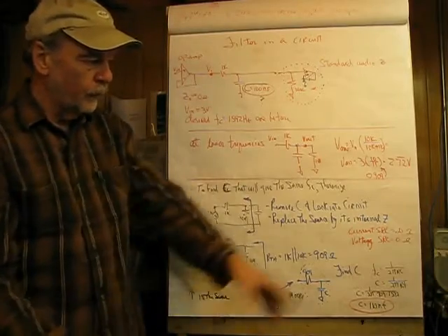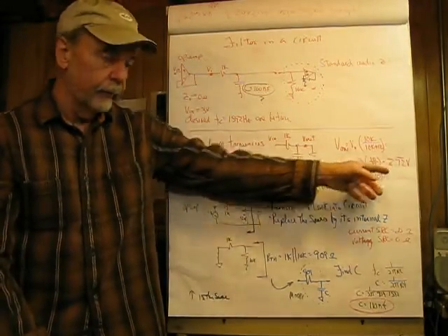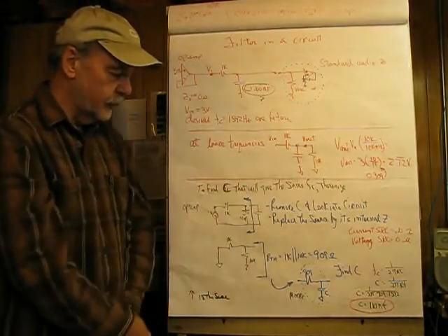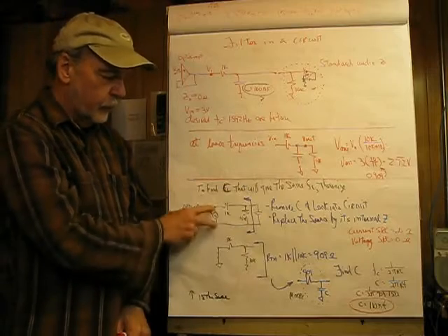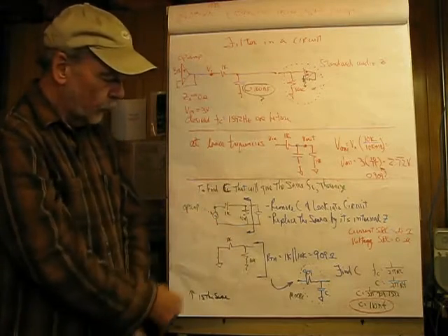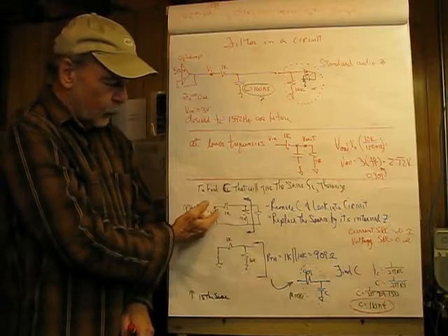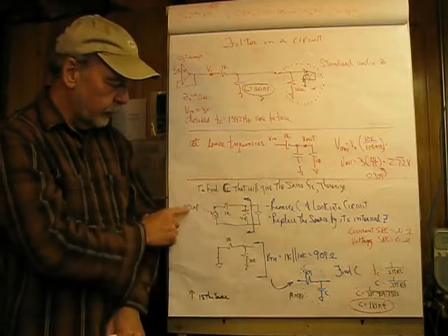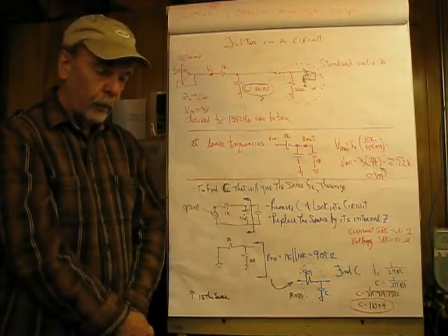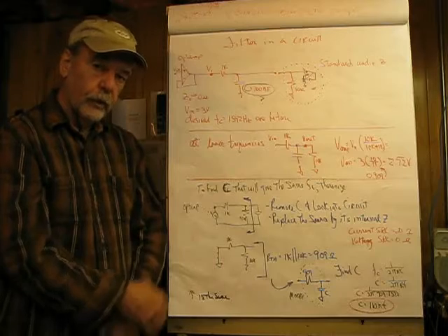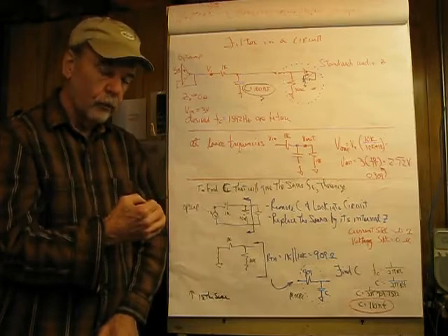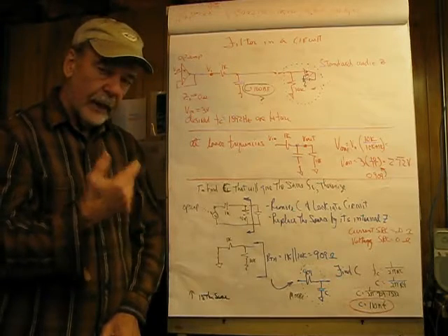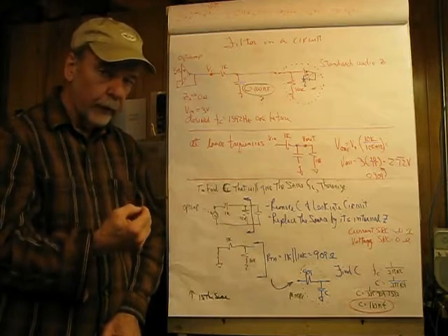Now we already know what VTH is, and that's this. And I did that without mentioning Thevenin, but essentially that would be part of this operation. And what I want to find here is RTH. So looking in here, we have to take into account the impedance of our driving source, and this is a voltage divider or op-amp. And what we know about that is that a voltage source's internal impedance is 0 ohms. A current source's internal impedance is infinity. And that's absolutely imperative that you know that.